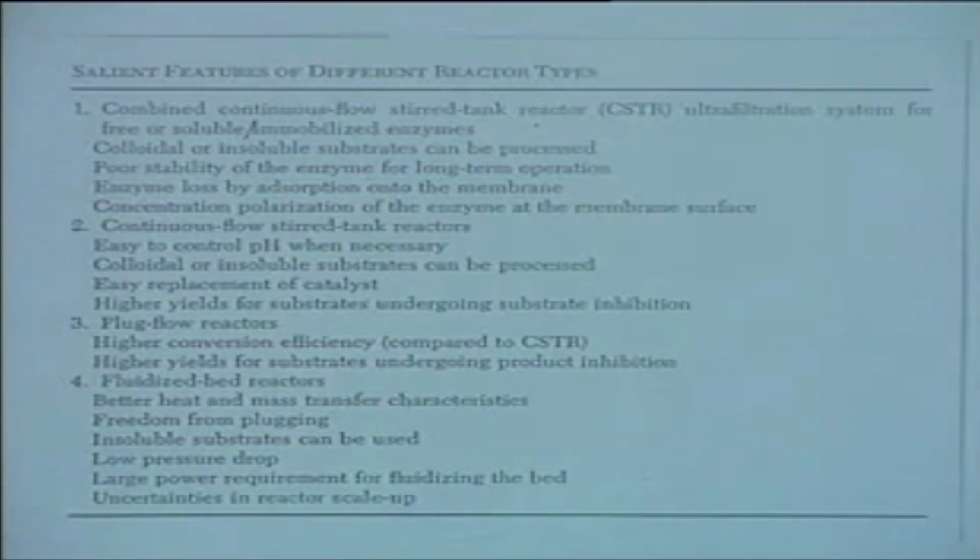Then the other category of enzyme reactors, fluidized bed reactors, as I mentioned earlier, are much better suited for heat and mass transfer characteristics, and freedom from plugging. Very often if colloidal substrates are to be used, a plug flow reactor faces the problem of plugging or choking of the column. In a fluidized bed reactor, insoluble substrates can be used easily.